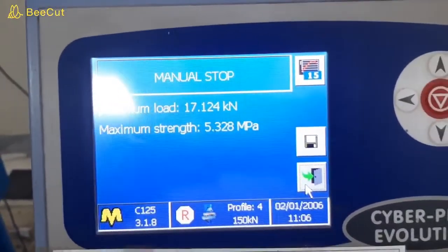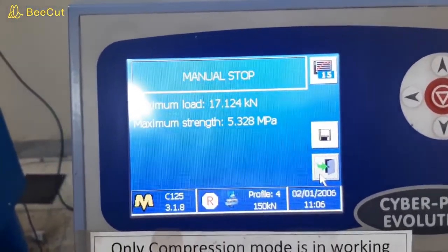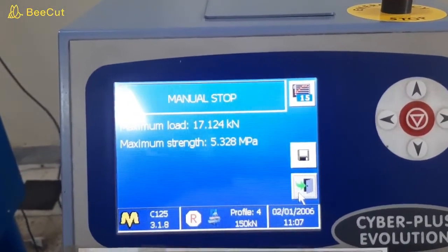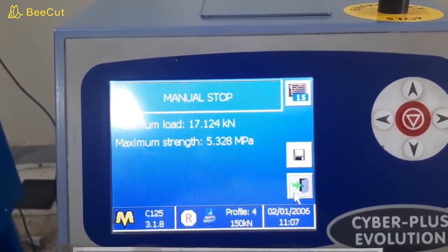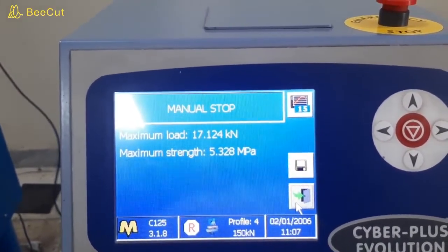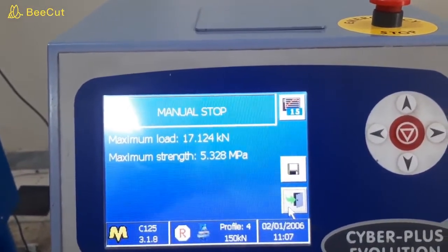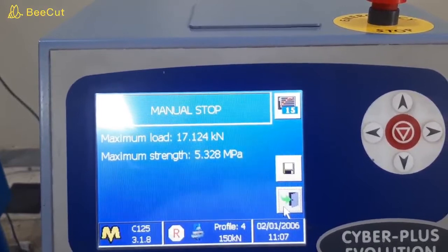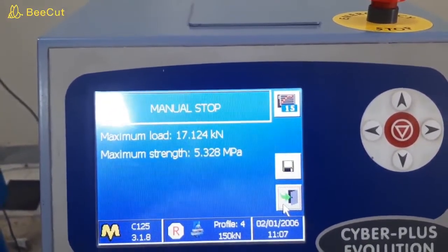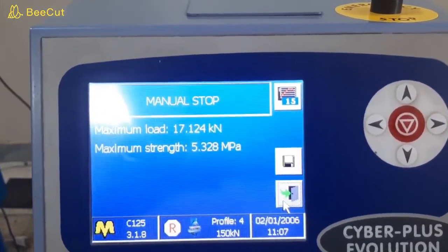In the same fashion we will test the doubly reinforced beam, and then we have to compare the results of all three beams. I will provide all the data of load versus deformation at the center point of all three beams and the maximum failure load, and then you will carry out the necessary calculation using the center loading formula for the flexure test to determine the flexure strength theoretically.